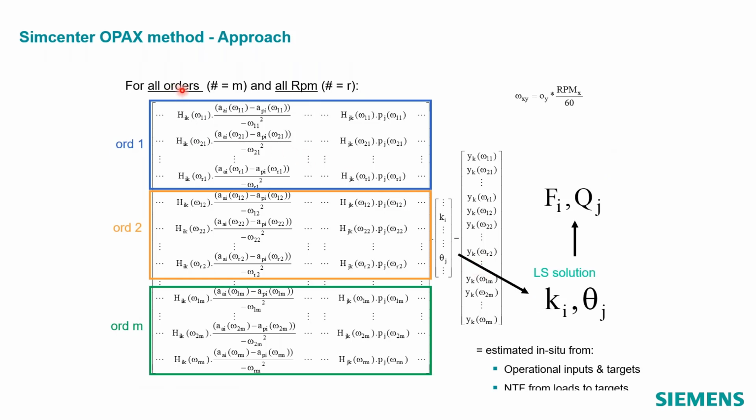So we can solve with operational data as orders, spectrums, autopowers, or octaves. This is using an example of an order. For every order, we can set up a bunch of equations where basically the response is due to the force multiplied by the contributions. We can set these equations up for all of the targets, all of the indicators, using all of the inputs and all the FRFs.